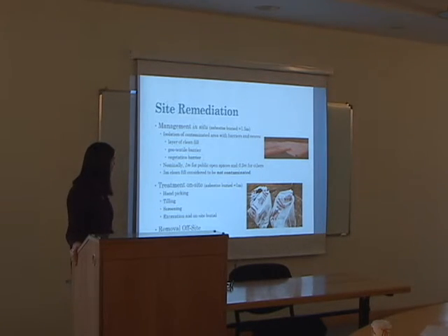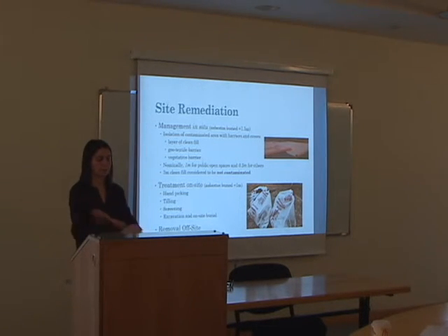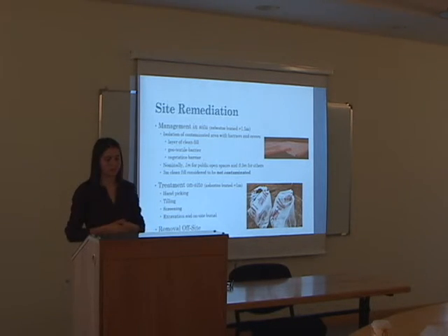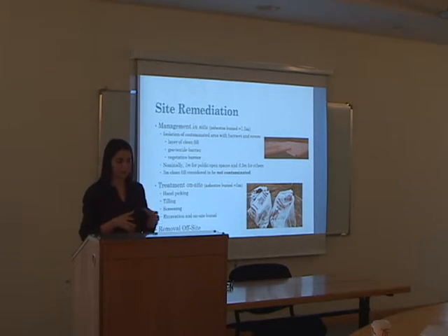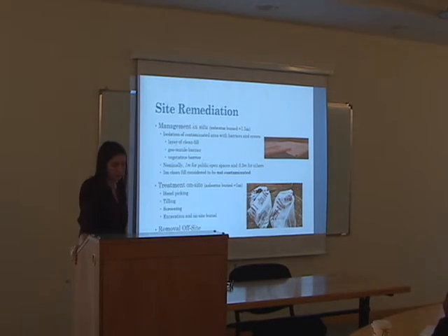Management in situ is the next step. It is done when the asbestos is buried more than 1.5 meters, and they isolate the area with some barriers, like clean fields of soil or geotextile barriers and vegetative barriers. 1 meter of soil is considered a nominal standard for public open spaces, and for other areas it is 0.5. And a 3 meter clean field is considered to be non-contaminated already.